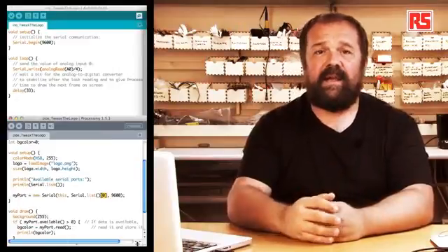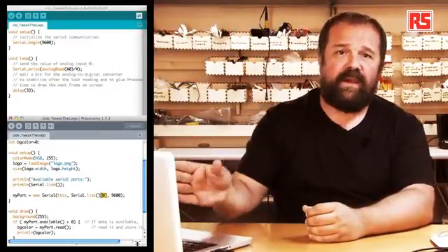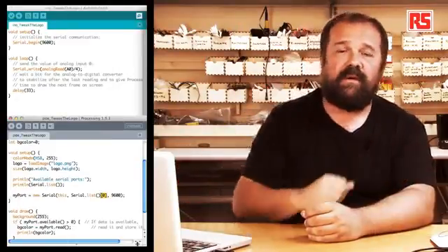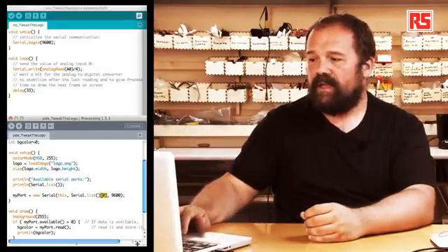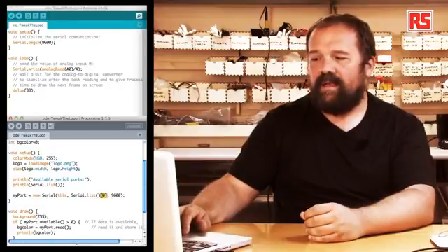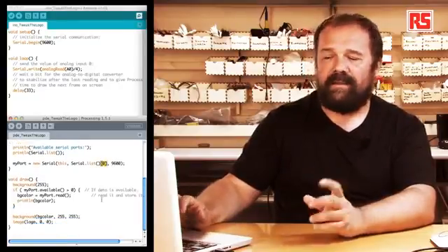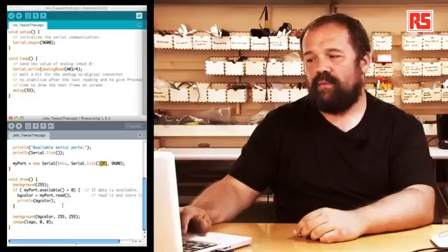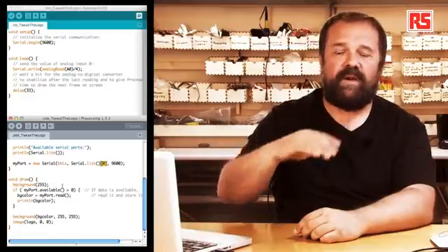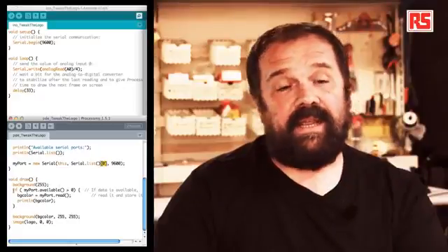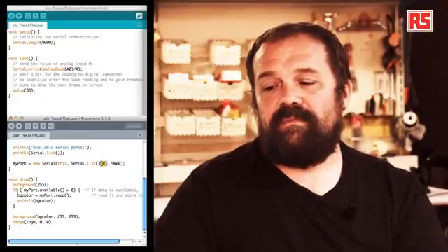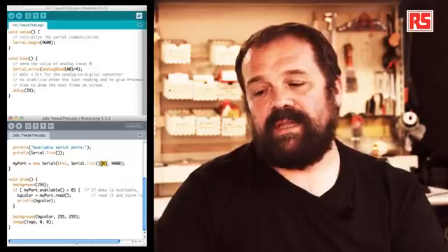After you're done that, the processing code is configured in order to talk to the Arduino, and we can then look at what happens in the loop. In the loop, we start off by setting the background to white by doing background(255). That sort of cleans the window at the beginning of each frame. Then there is an if statement that says, if myPort.available() is more than 0.